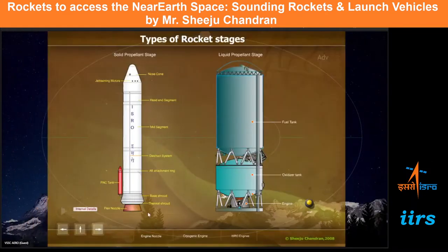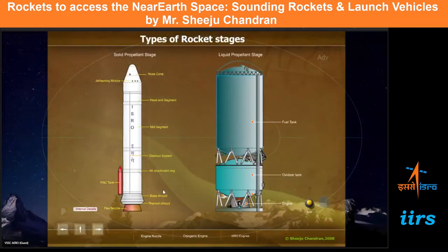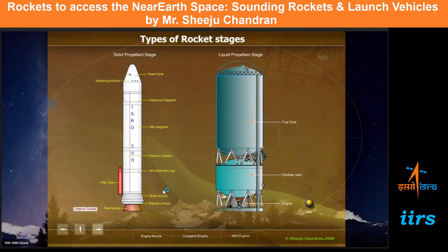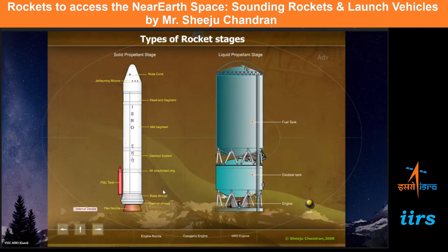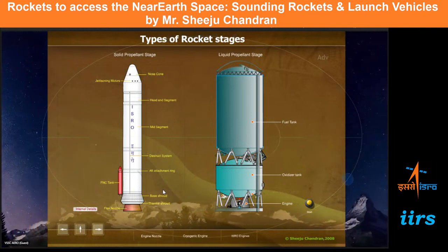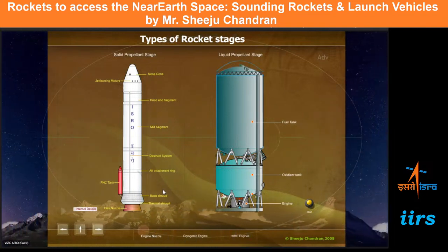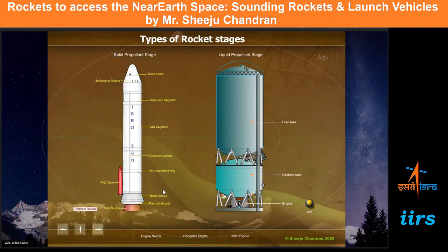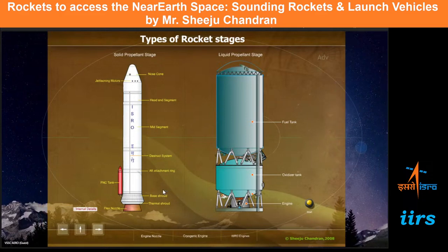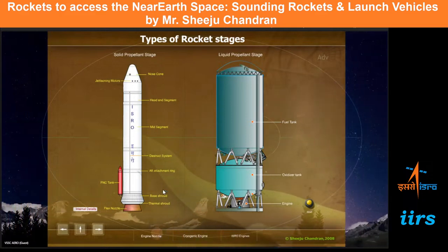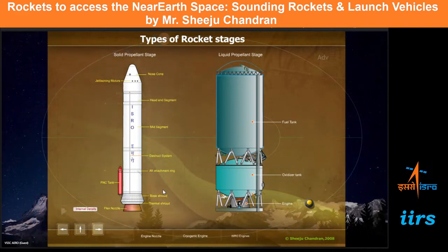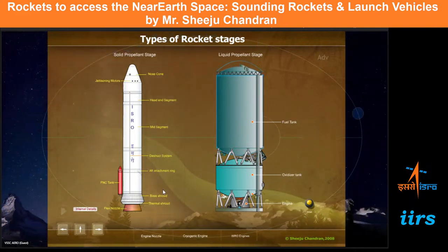Okay. Now, one important point. If you remember what I have mentioned, for rocket engines to function, you should have very high force in one direction, and the reaction of that will push the rocket upward. So what is basically this force? Mass flow rate into velocity. Or in other words, this entire process of combustion should produce extremely high velocity. Okay, not extremely high pressure, extremely high velocity.